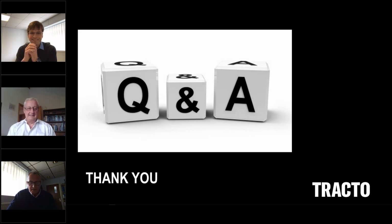Yeah, hi everyone. Thanks for the question, Peter. We've been asked that many times in the past, and I do believe if a customer has a project and he's looking to potentially purchase a machine from us, we can, but I would need to double check, manufacture and supply what we call a reversible machine, where when each pipe length's been installed, we can switch the machine to reverse, so the piston's striking more at the back to relieve or crack the machine from the pipe.